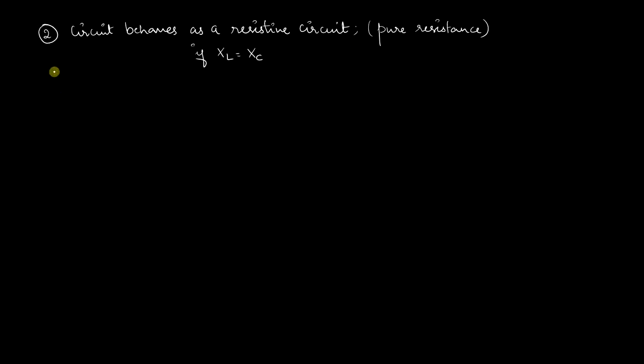Then the third property is that the power factor is unity. That is because power factor is computed as cos phi, and since there is no phase shift, phi is equal to 0, therefore cos phi will be equal to 1.